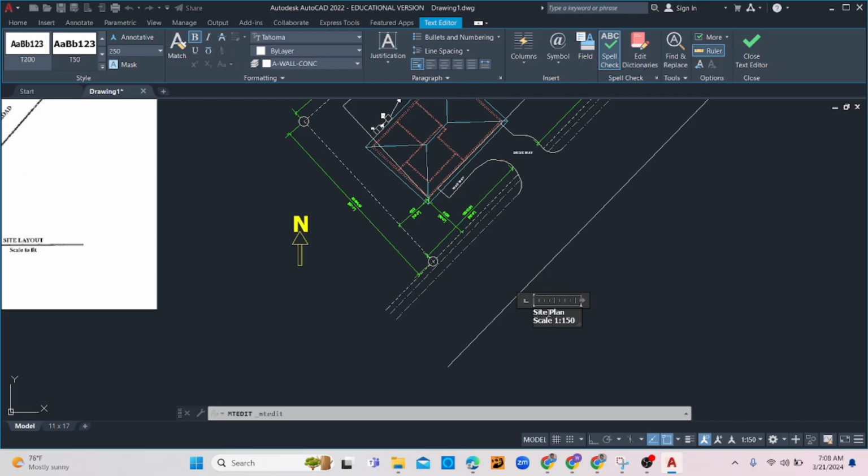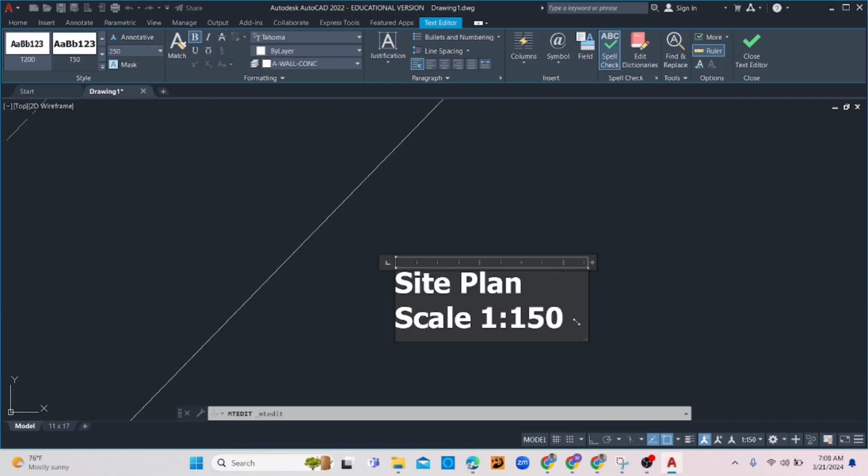All right. Down below, scale is 1 in 150. All right. Now I always have the scale being half the current size of the top portion. So that is 250. Let's just make this 125. All right. So half the current size. Let me underline this here using underline tool there. This text here, I want it to be to my right. Let me pull it over a bit. Alright, so that's it there.